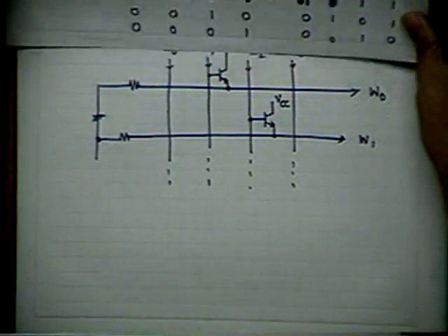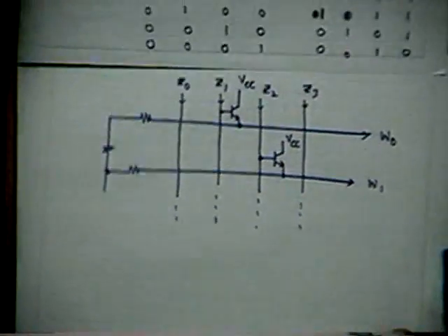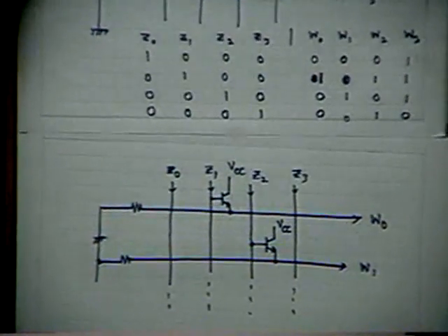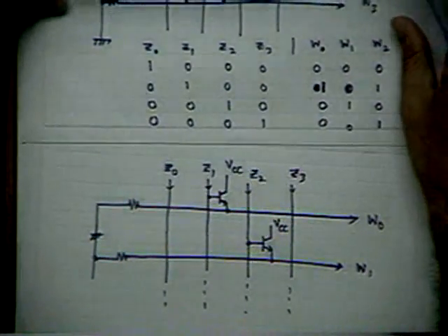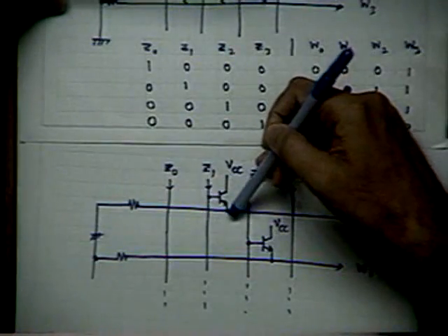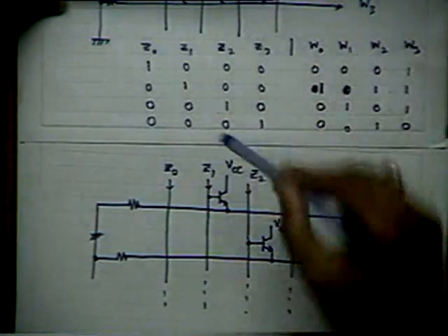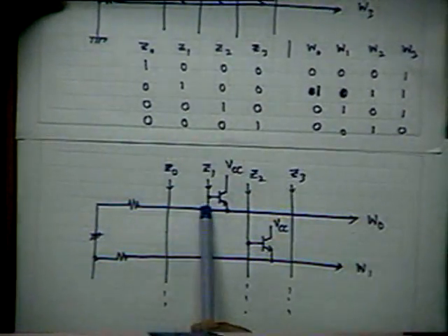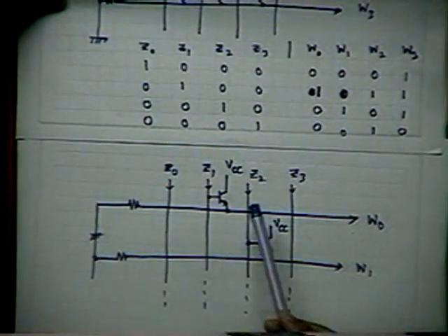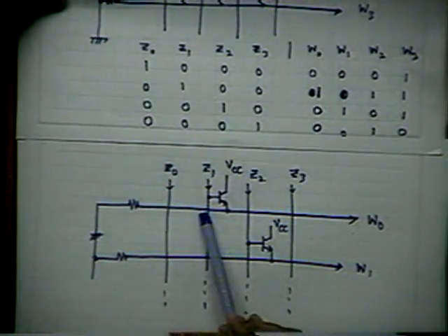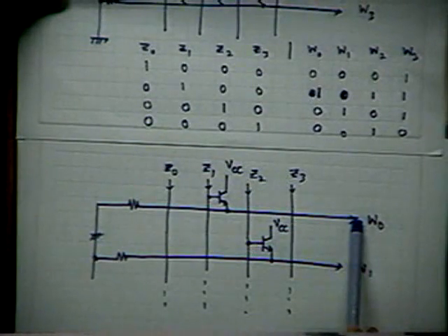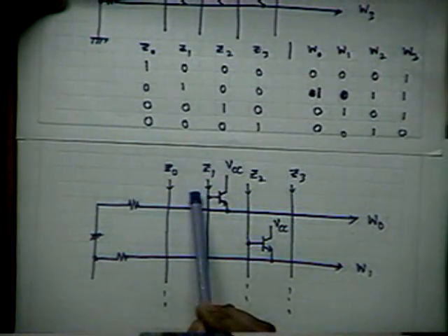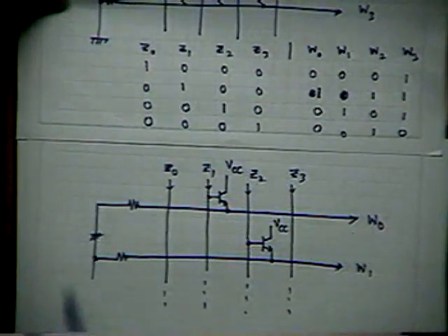Is there any advantage or is there a disadvantage? What is your comment? Because base current is always much less than the collector current. You are supplying from the input only the base current, which is beta times multiplied from the VCC supply, and then you get an output here. So your loading of the input decoded signal is much less here.